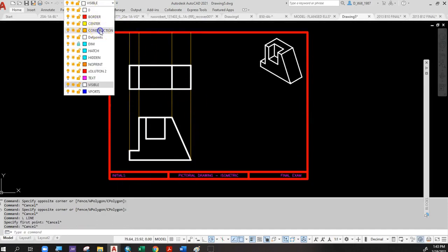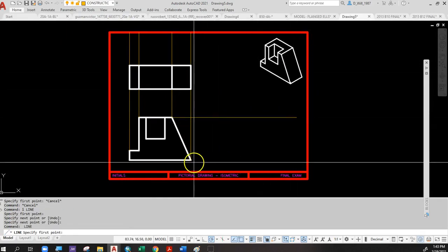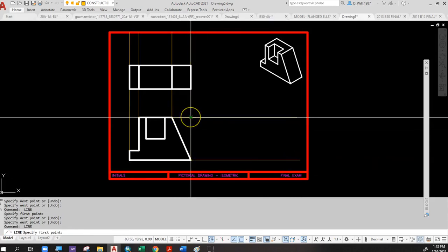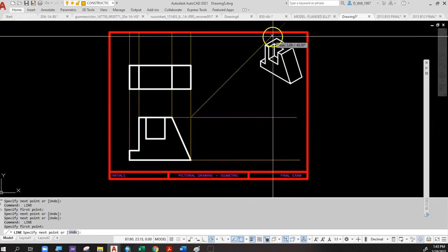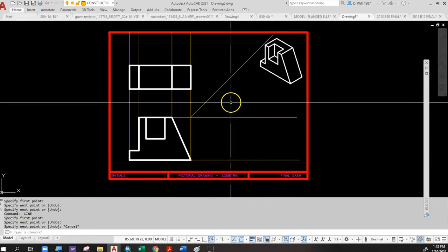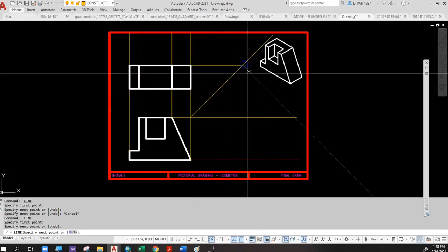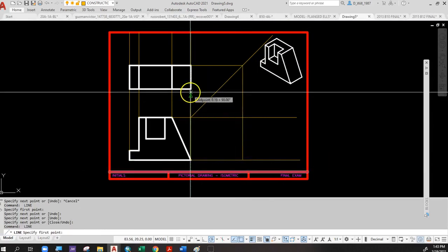We'll go back to construction. We will project over, and we'll project over. And then to get the top view into the side view, or to get the side view into the top view, you might remember this little thing called the miter line. And the miter line lets you take your measurements and locations from the top and telegraph them into the side.